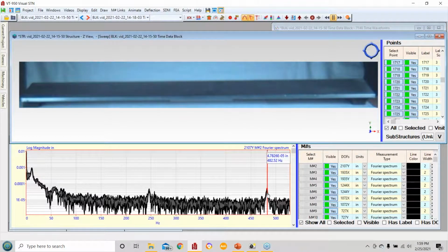Okay. Oh, we got a comment from Mark Senior here. When the force is not measured, you assume that its spectrum is flat. So the FFT of the impulse response is the FRF. Oh, okay. So there's no roll off. Flat force spectrum is used for all output only measurements, ODS FRFs and so on.